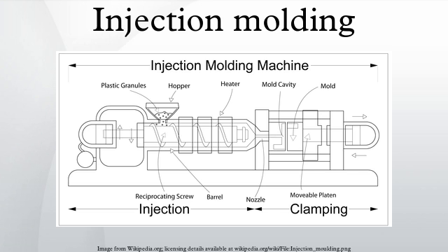Injection molding consists of high-pressure injection of the raw material into a mold which shapes the polymer into the desired shape. Molds can be of a single cavity or multiple cavities. In multiple cavity molds, each cavity can be identical and form the same parts, or can be unique and form multiple different geometries during a single cycle.